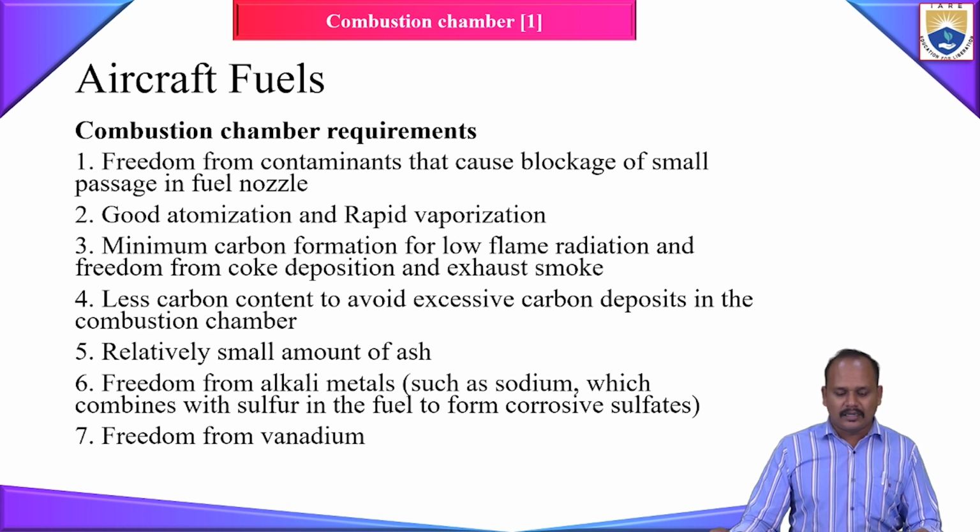And a relatively small amount of ash. You see, we are burning a huge amount of fuel, right? When it creates ash, it is going to create an environmental effect. So whatever fuel you are going to use should have less ash-generating capability. Freedom from alkali materials such as sodium.